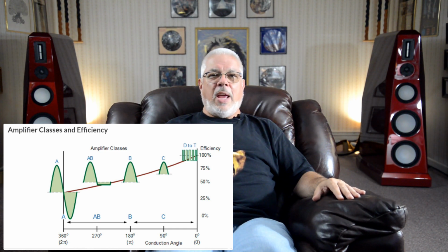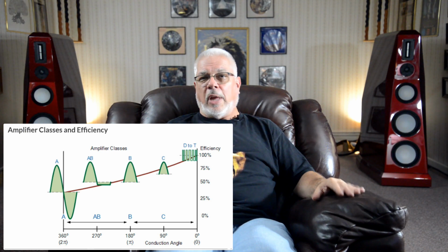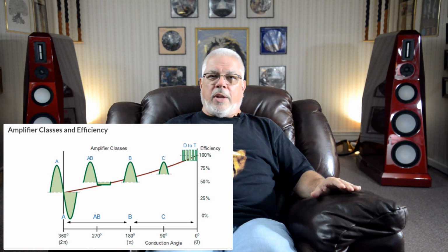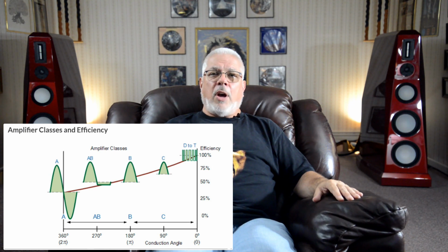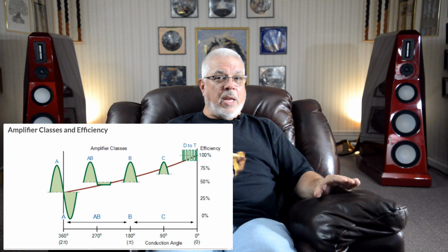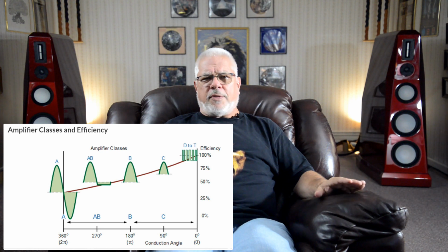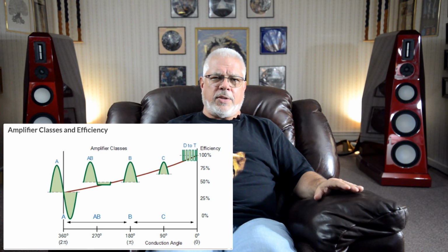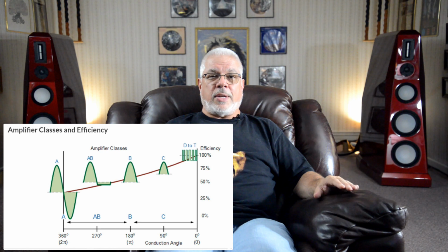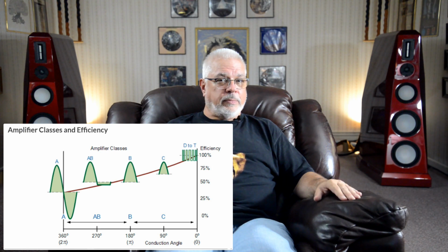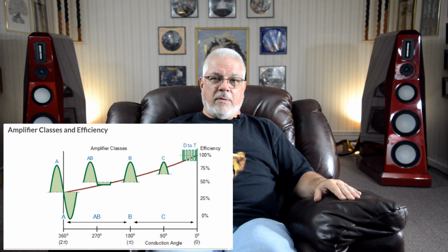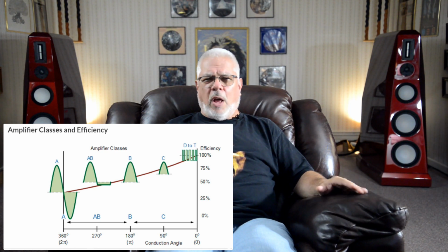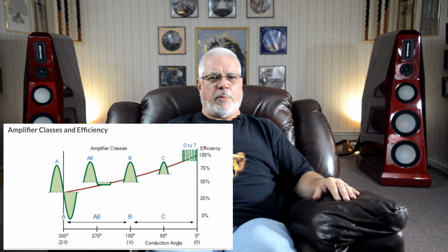Now, with Class AB, advantages include slightly higher efficiency, as well as their native linear behavior and lower distortion levels. They typically offer higher output power than Class A, and to my ears, all else being equal, they can offer much finer delineation of microdynamic events and offer a more authentic representation of dynamic scaling overall. On the downside, they still generate a lot of heat and generally fall well short of their theoretical maximum of 50% efficiency.